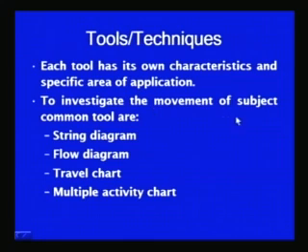To investigate the movement of the subject, the tools which are commonly used are string diagram, flow diagram, travel chart and the multiple activity chart. Each tool has its own specific features and suitability for a particular application. We will be talking one by one about each of these techniques.